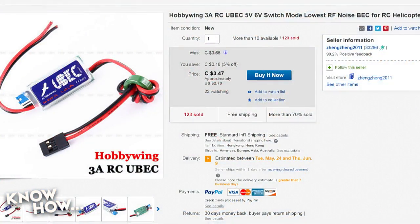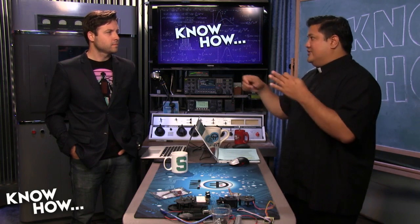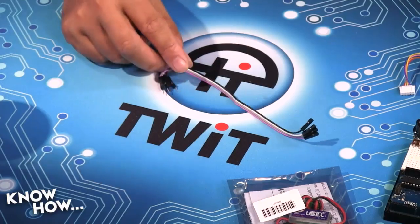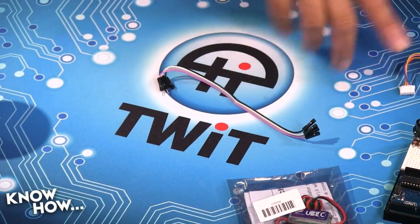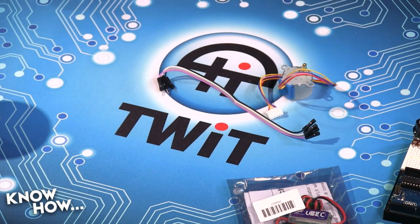You're also going to need jumpers. You can do it without jumpers just by having wire and soldering wires, but we want to have this temporary because we want to mock it up. You mean the jumpers for the breadboard and Arduino? Right, and they just look like this. So this is what a jumper looks like. I've got pins on one side, I've got a socket on the other. This will allow me to easily connect the driver board from the stepper motor to my Arduino without having to actually solder anything in or bodge together some wires.